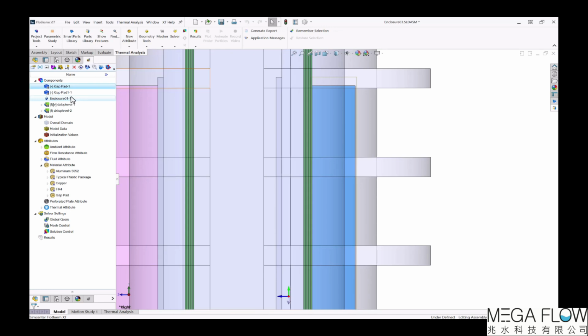In FLOEFD, the way you tell the software which material to use in overlapping geometry is handled a little bit differently. In FLOEFD XT, you just move the components up and down in the tree hierarchy, but in FLOEFD, you have a separate window called Materials Priority, where you specify which materials should take precedence based on the priority list that you can modify. Now, this will be more efficient for complex models that have a lot of objects and material assigned. It will be a lot more efficient in FLOEFD's method of handling overlapping geometry.